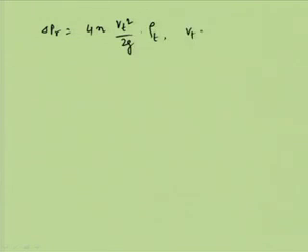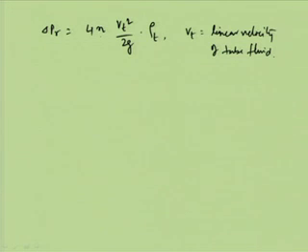Now, another part is delta PR, this is given as 4n into Vt square by twice g into rho t. Here Vt is the linear velocity of tube fluid, okay, and other terms are known to you. N is the number of passes, and delta Pt total is equal to delta PF plus delta PR.